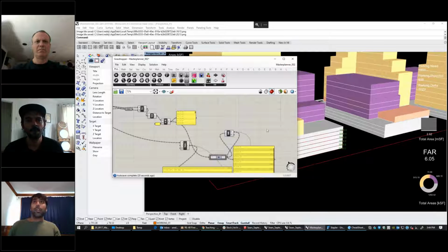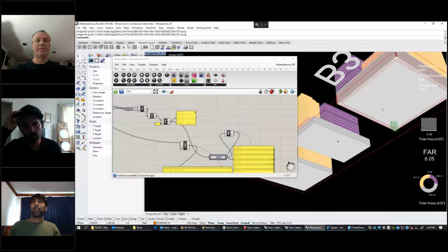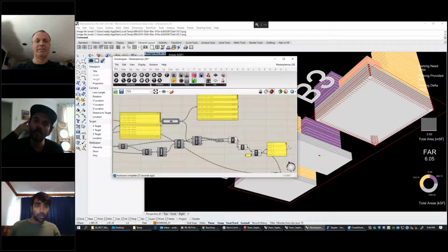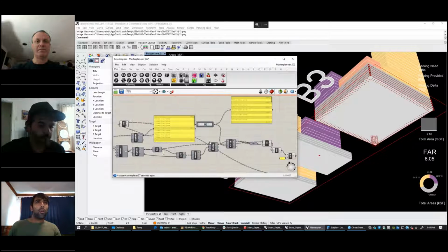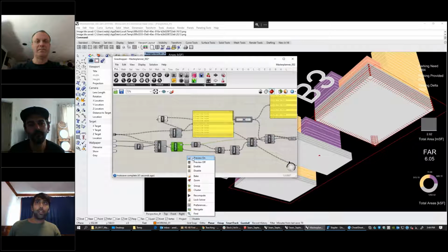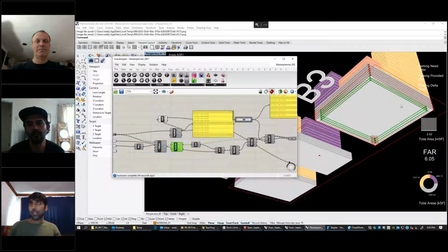Yeah, so now let's go back to the interior. How do you get that interior drive aisle? So let's see. We need to get our interior edges here, right? So right now, let's go back. Where was our interior edge? Was this guy, right? So that's this. And now we need to offset this again 24 feet for our interior drive aisle, define the interior box, and start laying out rows and rows of parking.